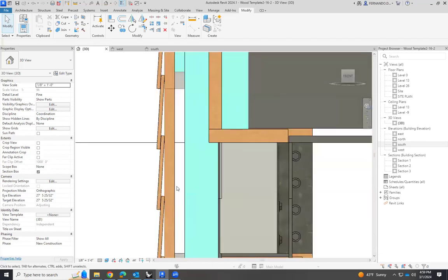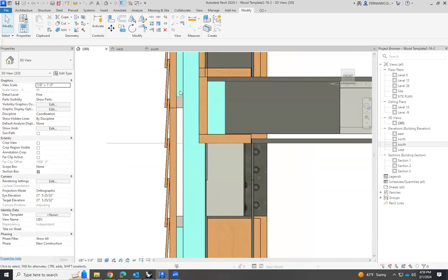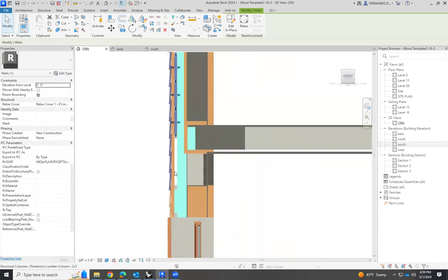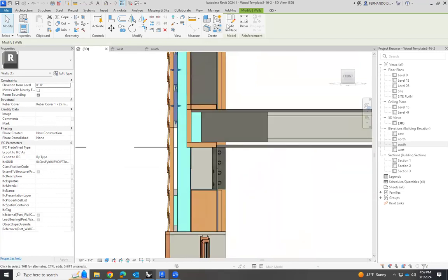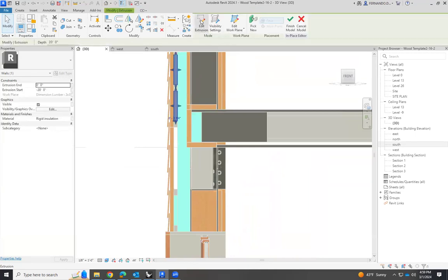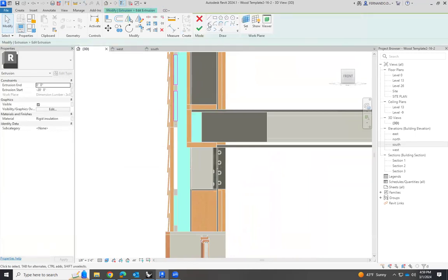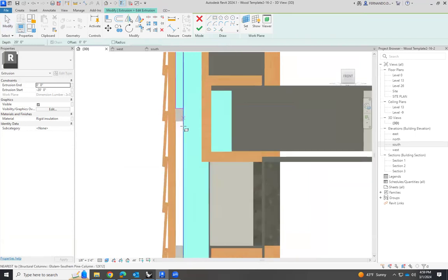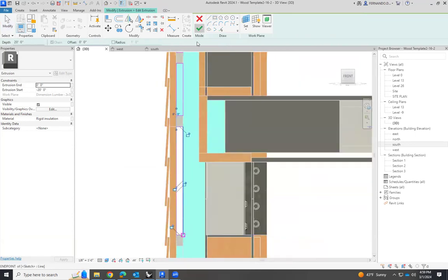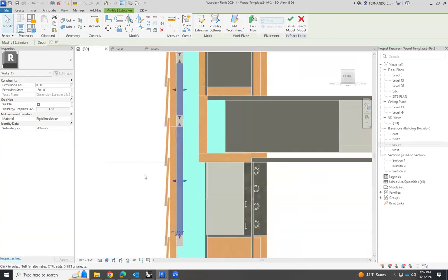And we do have this rain screen that can fill again with this layer of thermal insulation, or I can leave it that way. So if I edit in place this, and I edit the extrusion, I can always create another rectangle of rigid insulation here. There you go. Okay, so now we have thermal insulation here as well.